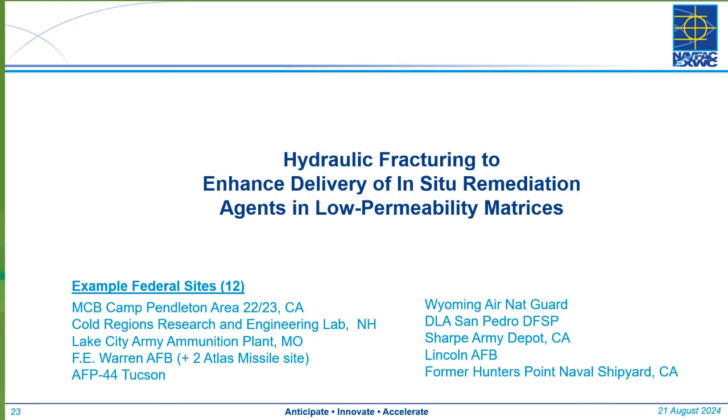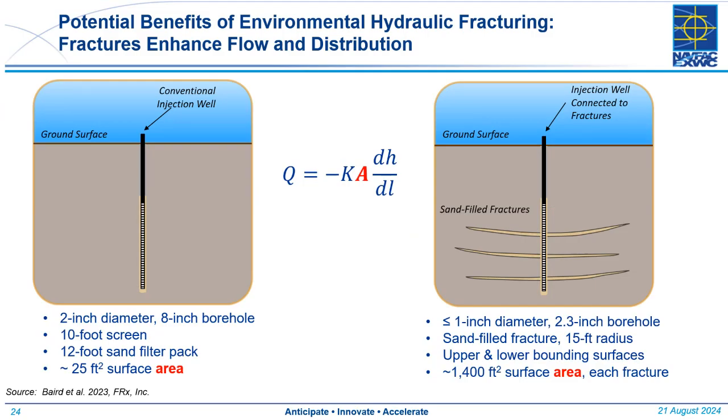The next tool we want to talk about is hydraulic fracturing. And of the options presented today, this one is probably the most mature, used most widely at DoD sites. We identified 12 different federal sites where this technology has been used. And you can think about hydraulic fracturing in terms of the Darcy equation, where Q is volumetric flow, K is hydraulic conductivity, A is area, and dh/dl is hydraulic gradient.